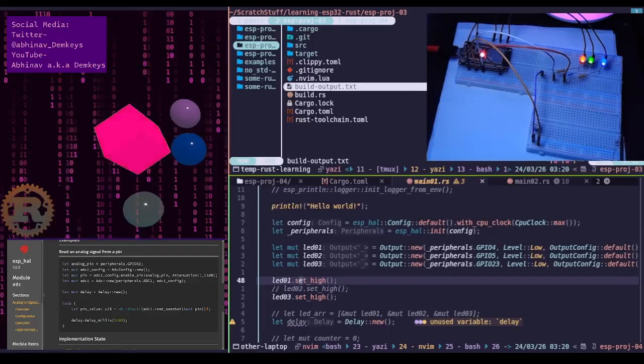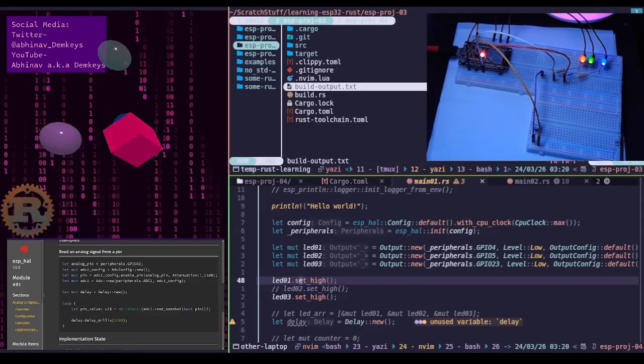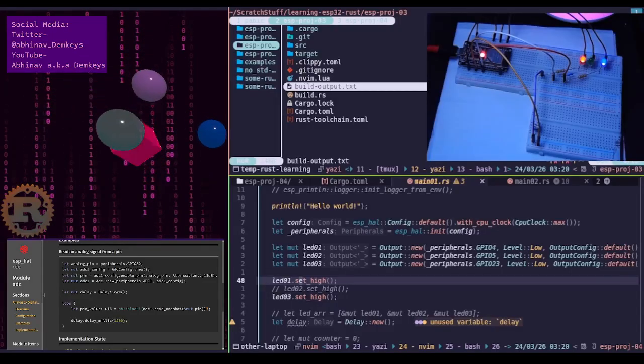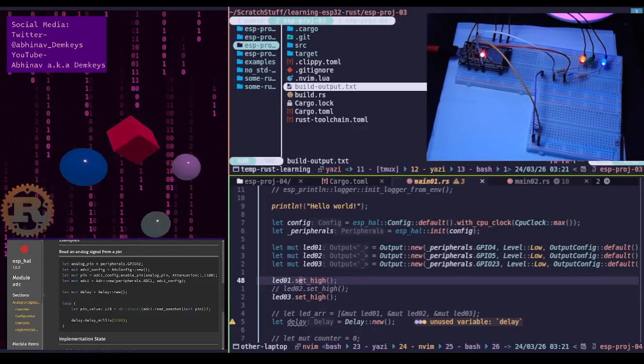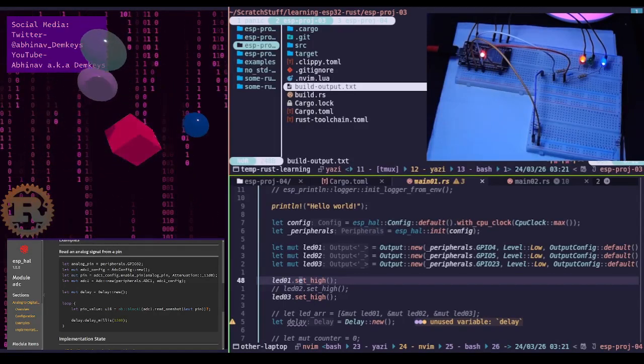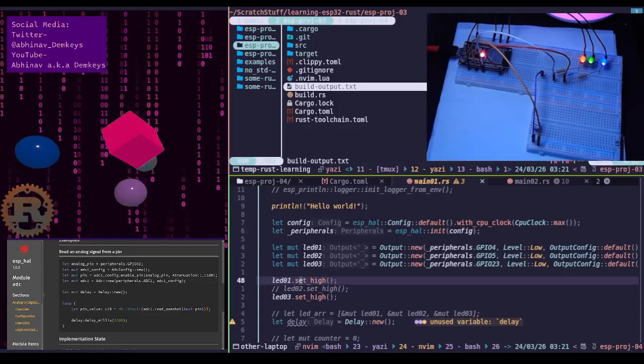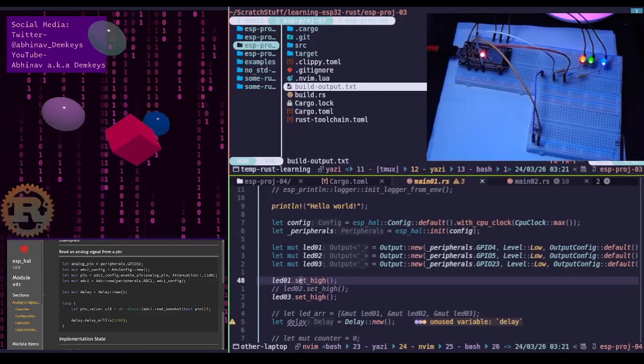So that told me that there's some issue with heat going on. And in this case, it turned out that the heat was way too high. And so any flux that I was putting onto it wasn't really helping because the surface would get oxidized very quickly.